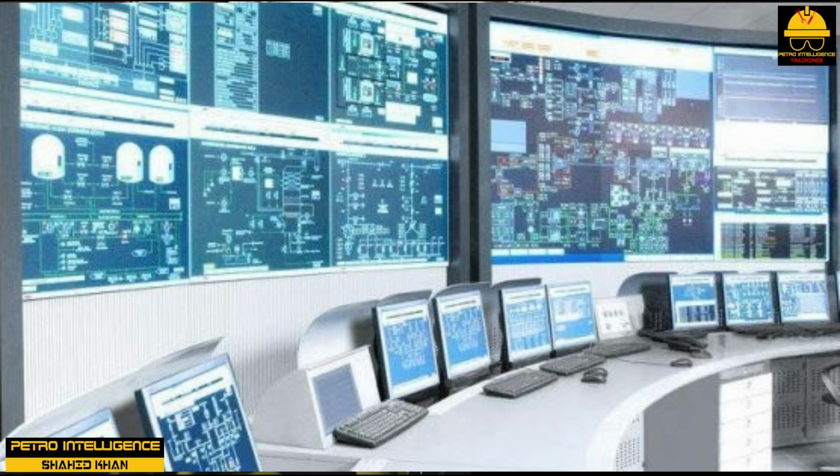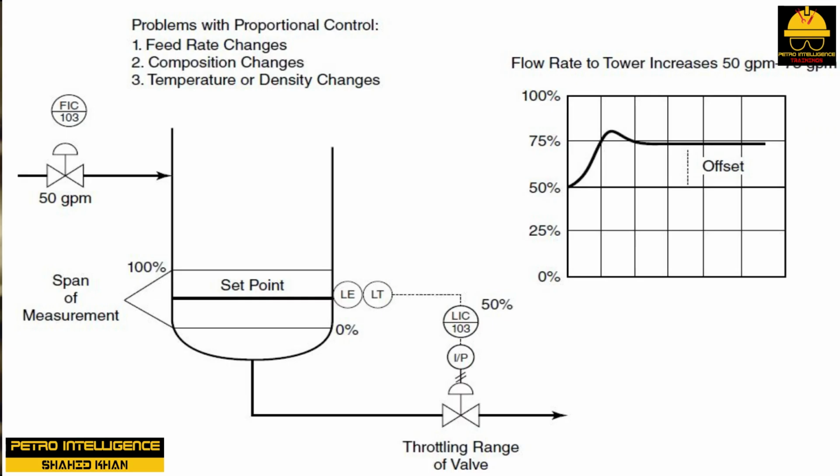The primary reason was the ease with which a DCS could be installed and the relatively few wires required to do it. Most modern plants include a combination of all three systems: pneumatic, electronic, and digital. The diagram of a control loop will identify the type of controller: pneumatic, electronic, or DCS. For example, in the picture, the diagonal lines between the transducer and the valve signify pneumatic control.